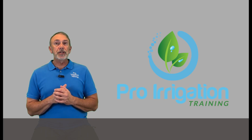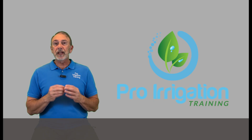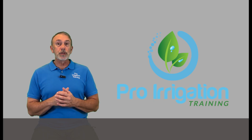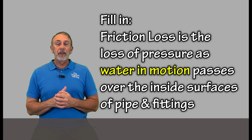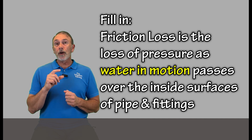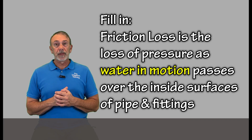And that's why we try to use best practices when we design an irrigation system. When we're doing the design of it and calculating everything out, we want to be precise in what we're doing because we're trying to control the velocity, and therefore we're trying to control the friction loss. Now, the definition of friction loss is the loss of pressure as water in motion passes over the insides of pipe and the fittings.